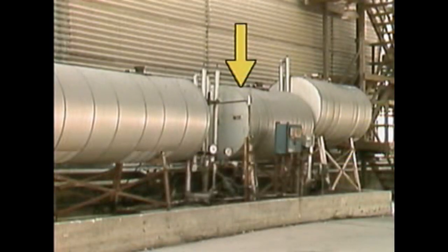There are also chemicals called scale inhibitors that protect equipment from scale formation. Some scale inhibitors form a protective film on surfaces. Others react with scale-forming compounds to form compounds that won't stick to the inside surfaces of pipes and equipment.